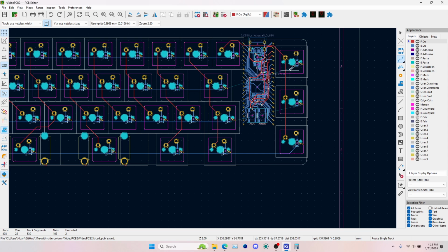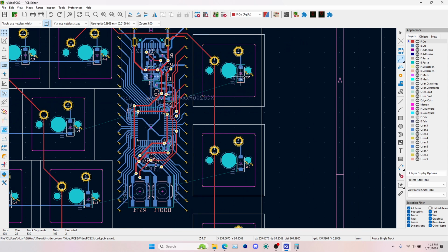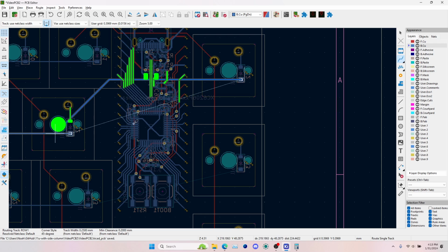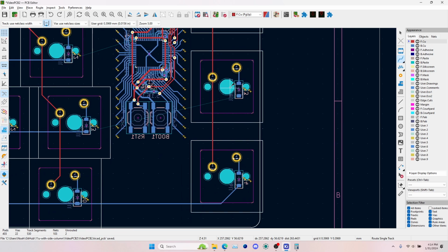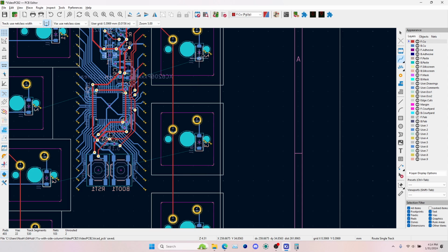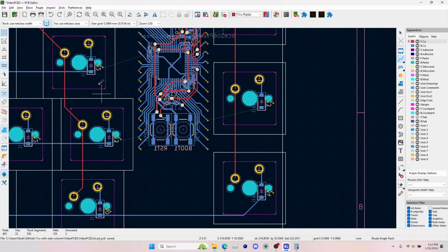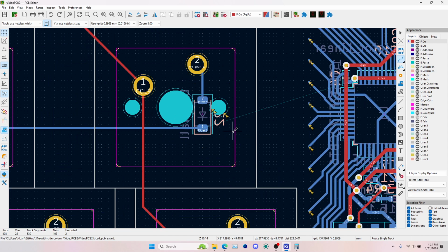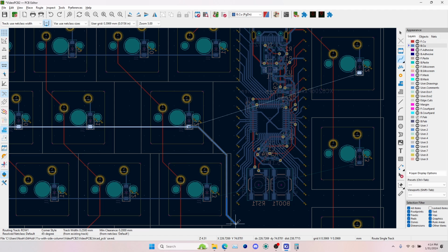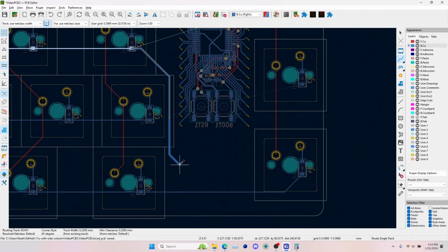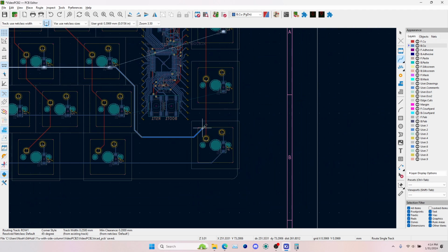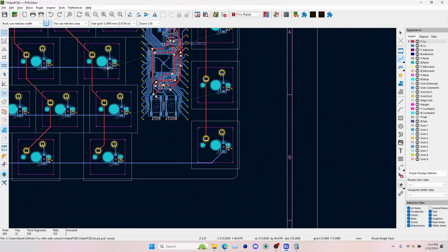The last thing to connect are these two switches. Their rows go straight through all the components. But what we can do is bring that, like we said, down and around, and then bring it back up. But like we said just now, we don't want to put a big blue trace that goes down across all the I/O and bring it around. We'd actually want to bring it through a via.